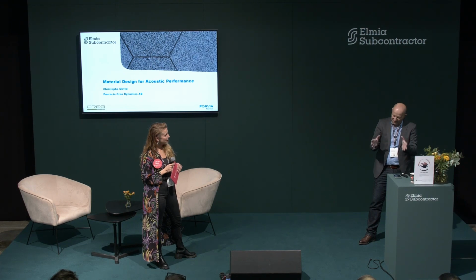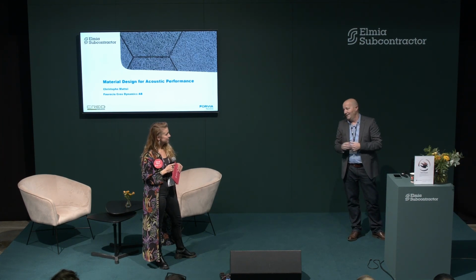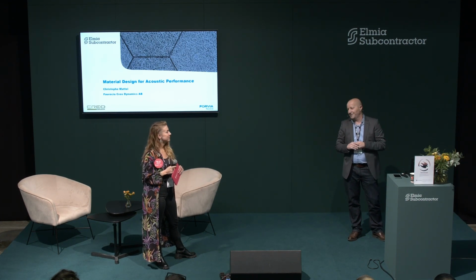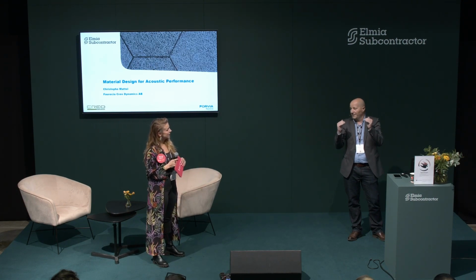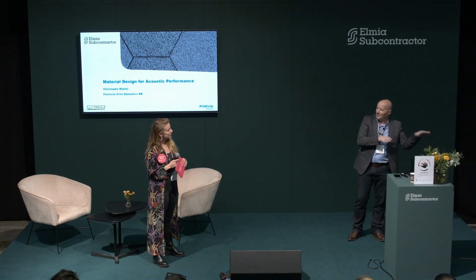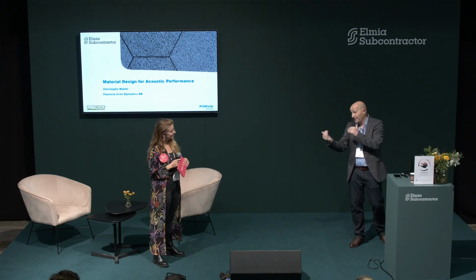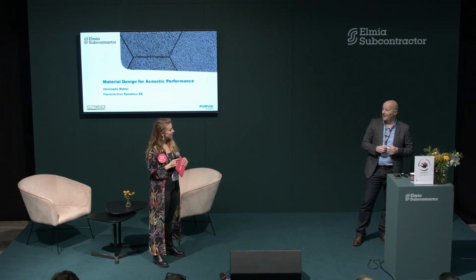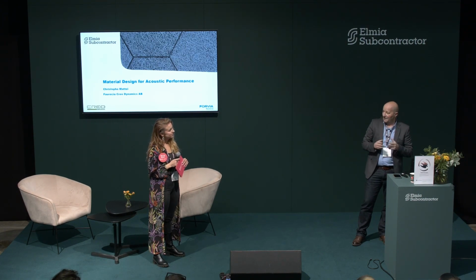Today, the expectation of comfort in an electric vehicle is that you are going to sit in a silent car. After 40, 50 kilometers an hour on a road, the sound level in the car is absolutely the same as in an internal combustion engine car. And this mismatch with the expectation of the end user is pushing this type of active noise control technique a lot.